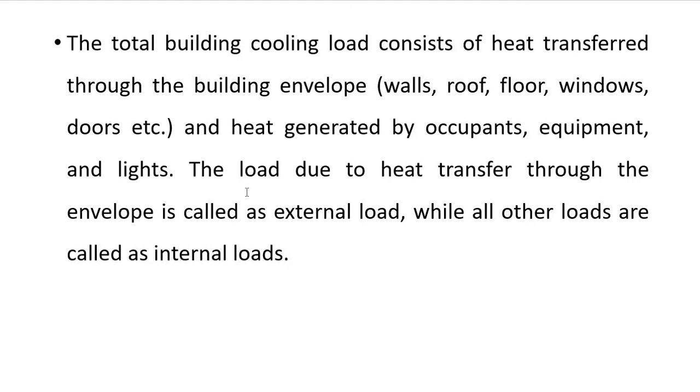So we can define what is meant by an external load and internal load. The load due to heat transfer through the envelope, envelope means the walls, roof, floor, windows and doors, is called external load, while all other loads are called internal loads.